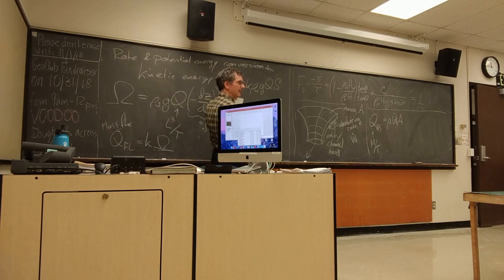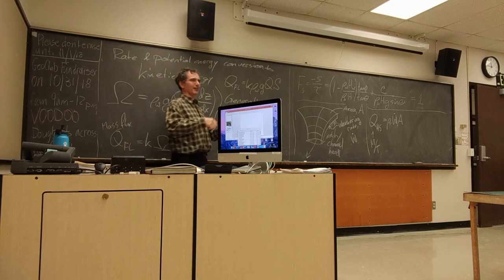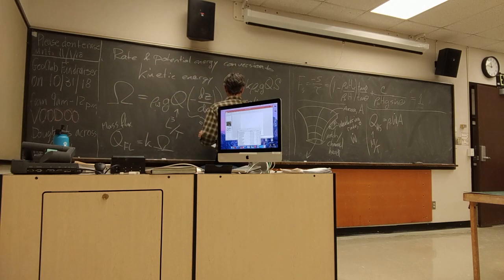But you know, I'm not real confident about this. Yeah, Gene. I was going to ask what sediment size. Yeah, see, it's all going to matter. So you know what? I'm going to go ahead and generalize that a bit. Because again, I don't know if it should be shear stress or stream power or even raised to some exponent. So I'm going to just make it a bit more general. Say that my fluvial mass flux is proportional to discharge to some power, slope to some power.